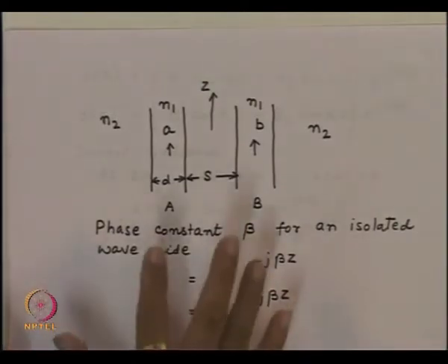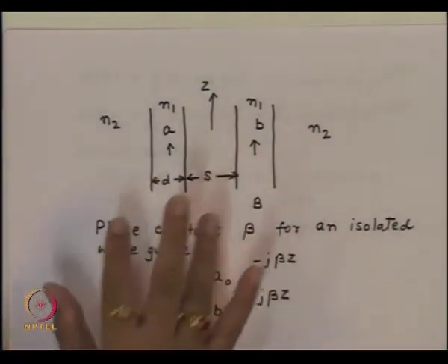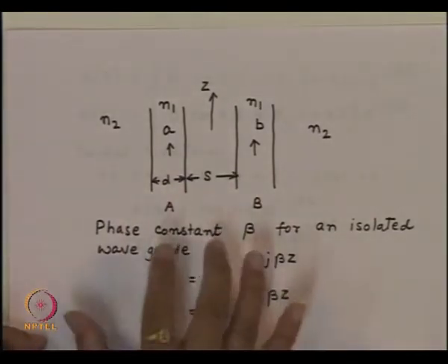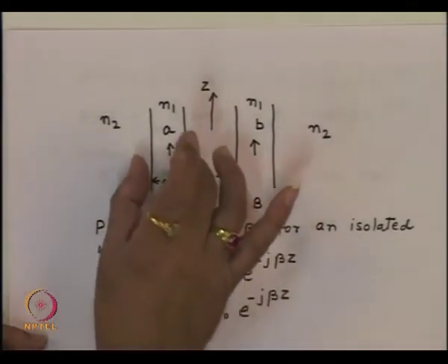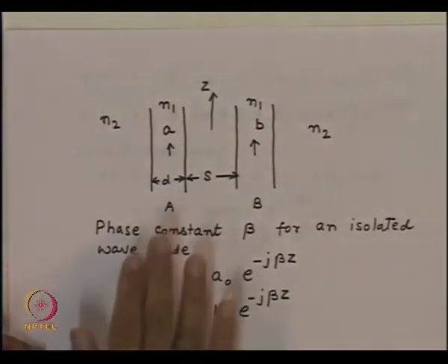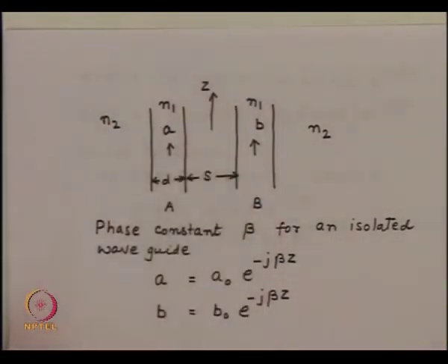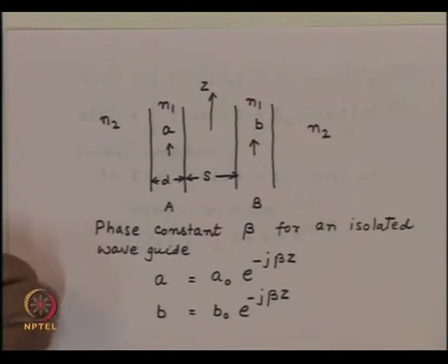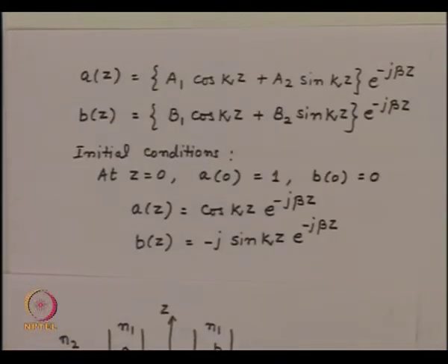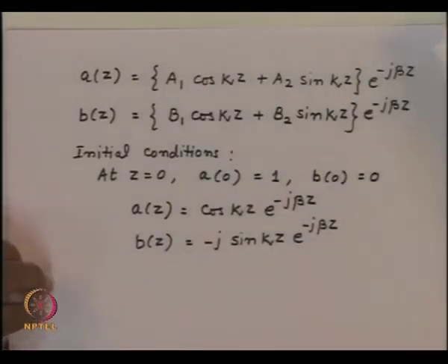So now when the interaction between the two waveguides starts taking place, essentially I have the variation in the amplitude of the signal and the phase, which is essentially representing a travelling phenomenon. So that's the variation we get here.